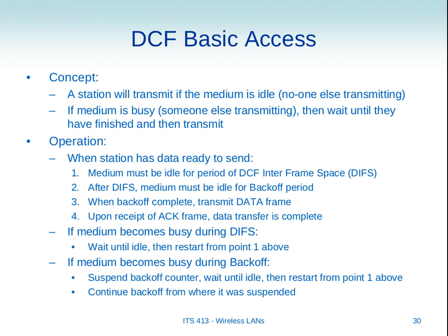How do I know no one's transmitting? Well, I turn on my receiver. If I receive nothing for some period of time, then I'll assume no one's transmitting. If I receive something, then I assume someone else is transmitting. So we can detect if someone's transmitting by listening using our receiver. A station will transmit if the medium is idle.